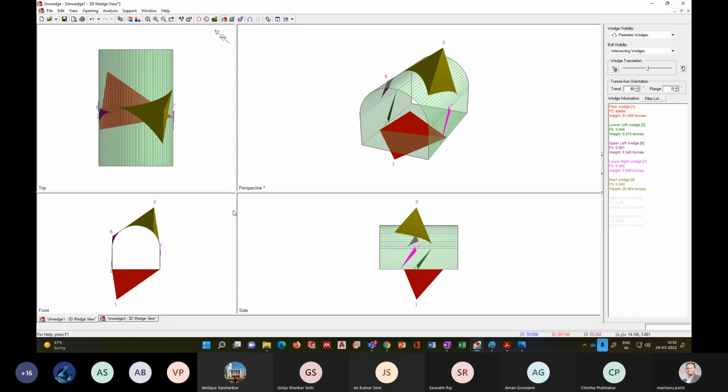Okay. So during our site investigation program, first we see what the wedges and joint sets are at that location. We get those orientations, and then we try to orient the excavation such that our support requirement will be less. Is that clear?